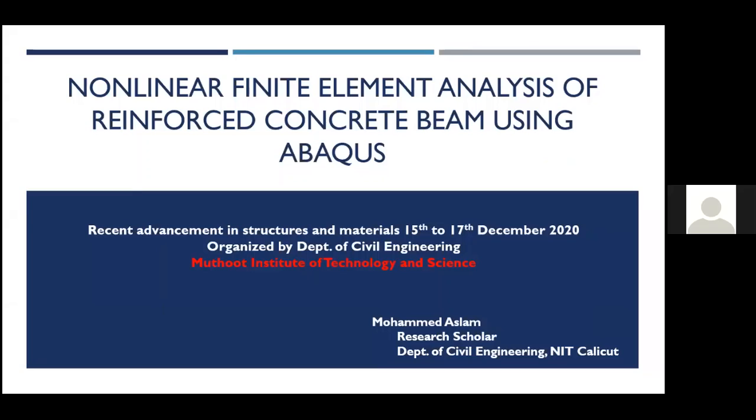And in this session, we'll be discussing nonlinear finite element analysis of reinforced concrete beam using the software ABAQUS. Now, before going directly into the software and discussing the modeling and all, first let us understand some basic concepts on the concrete behavior.